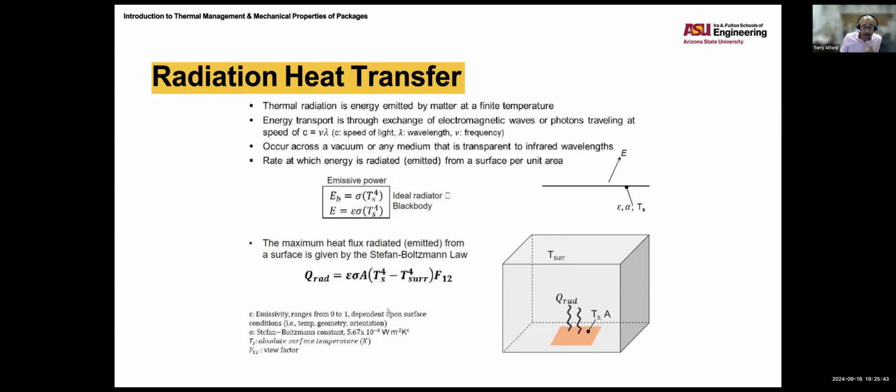Yes. If the TIM and the heat source have the same area, and the dimension of the heat transfer needed for the case of the TIM is small compared to the other two directions, yes, we can utilize the 1D resistance network. And for good engineering practice, we need good design and good experimental results.